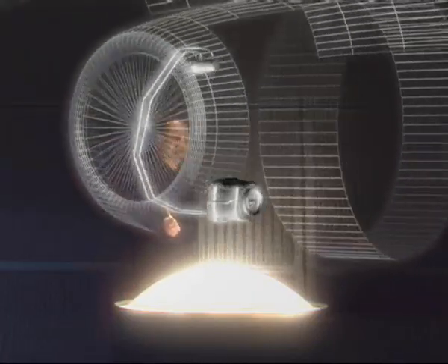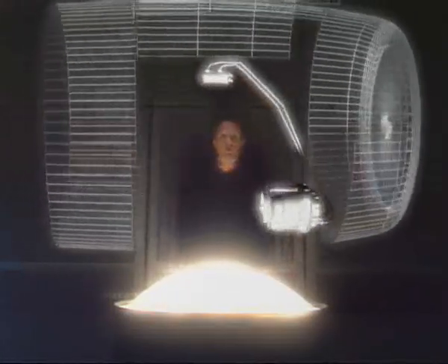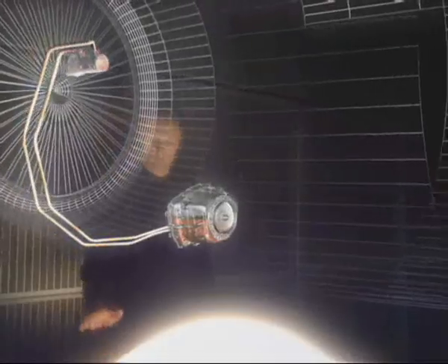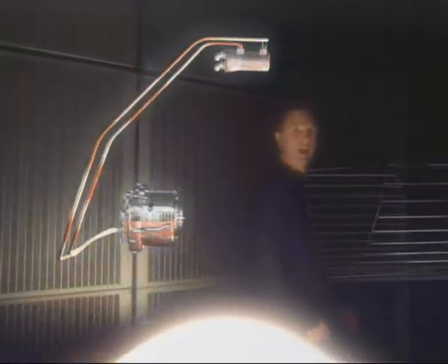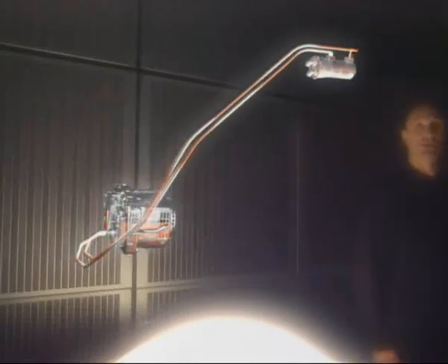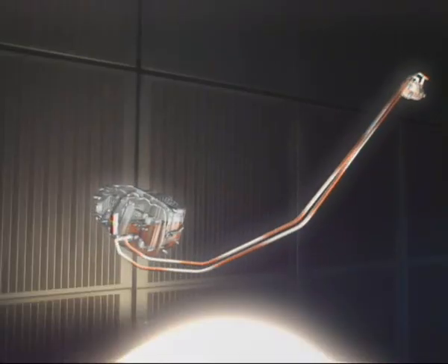You recognize the IDG system: the IDG, the external cooling circuit, and the IDG oil cooler. During operation, the oil is pumped out of the IDG to be cooled down in the cooler. Then the cooled oil comes back into the IDG.